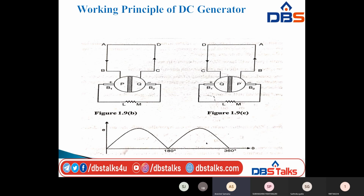The change over of segments P and Q takes place when the flux linkage or induced EMF is minimum. So when the flux linkage or induced EMF is minimum, the segments P and Q are interchanged. In a generator, the split rings are called commutators.